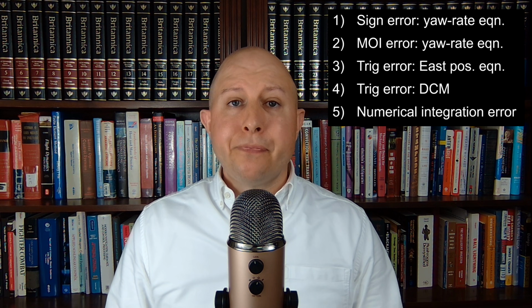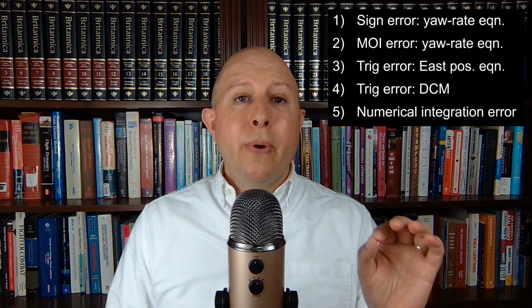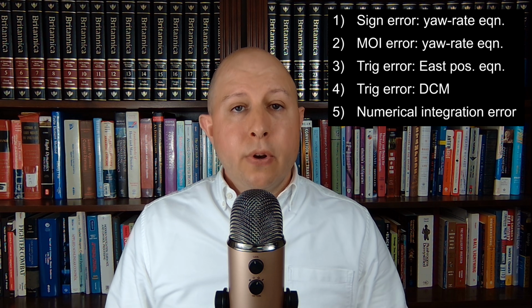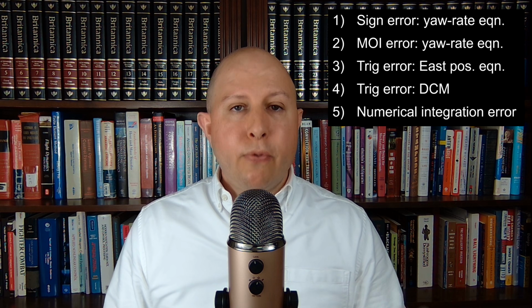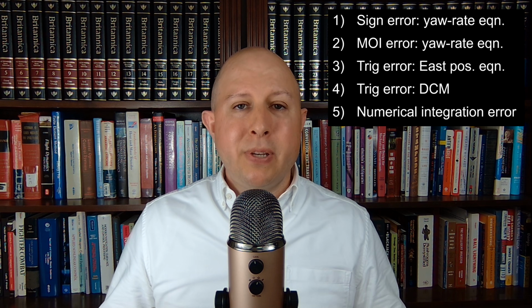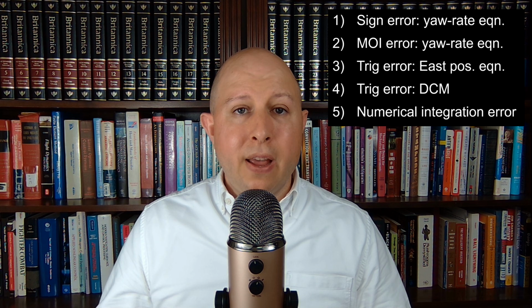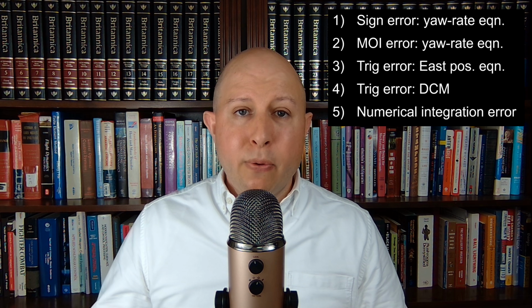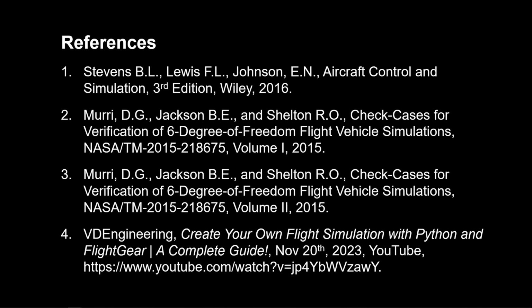And finally, a very tricky error. We had to resort to a higher order integration method because the first order forward Euler method that was originally used caused error to build up to the extent that it created differences with the verification data. A second order Adams-Bashforth method was used, and then finally a Runge-Kutta fourth order method was used to get verification data to match our sim.